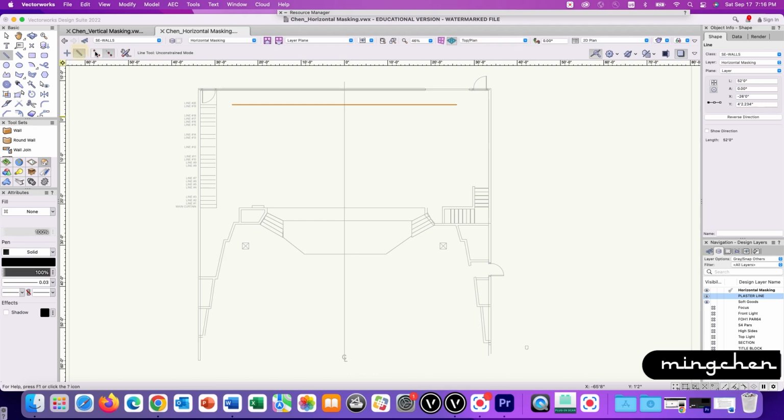Draw a diagonal line starting at the critical seat box located on the right side of the audience. Run the line through the left corner of the proscenium arch all the way to the stage right side of the offstage space and make the second click. This is the first referential line.